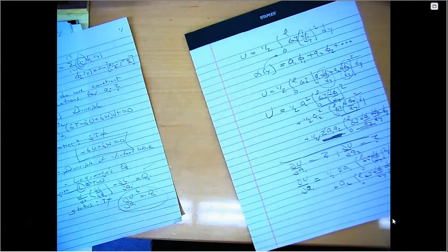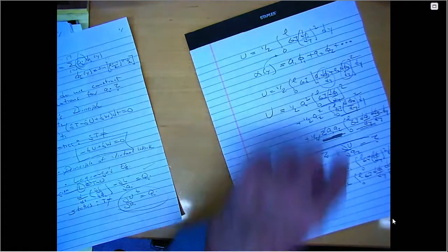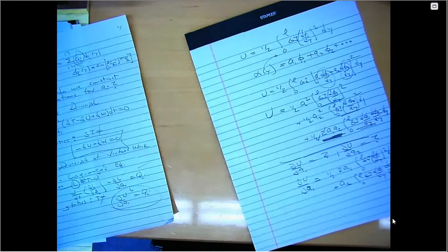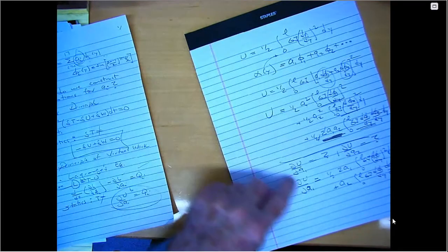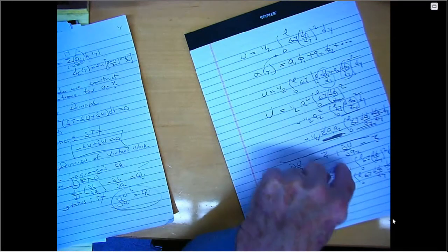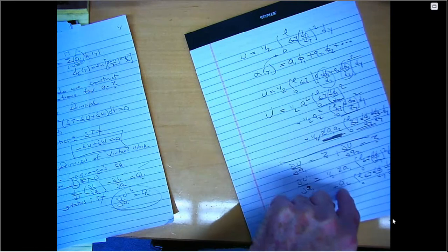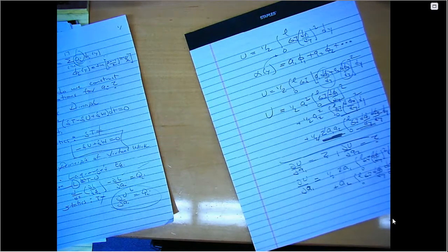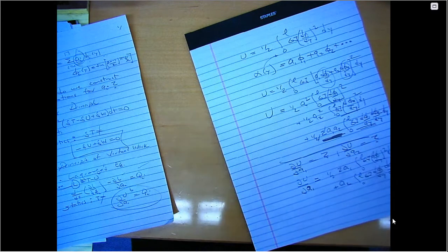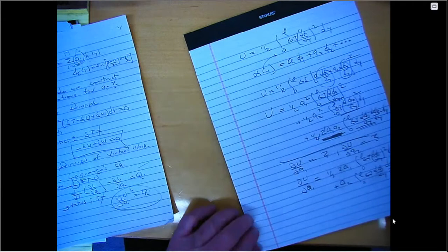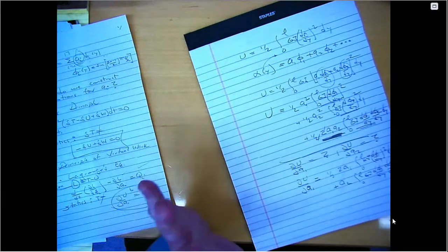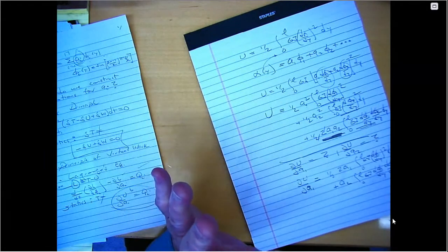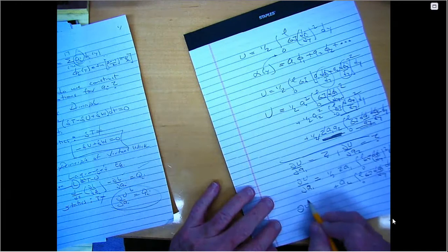And so in the equation for i equals 1, in general there will be two terms, one of which will involve A1 and one of which will involve A2, except for the special case of Gj constant and the artfully chosen mode shapes I gave you. This term probably is 0. I'm almost certain it is, but you can check it, right? Okay. So that's that part. Now we need to compute. Remember what the Lagrange equations are?